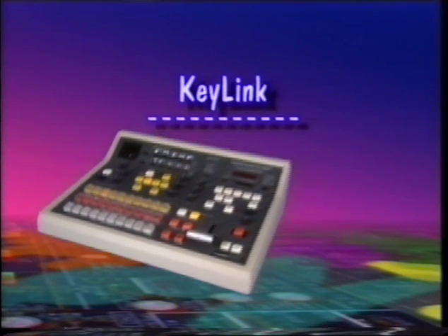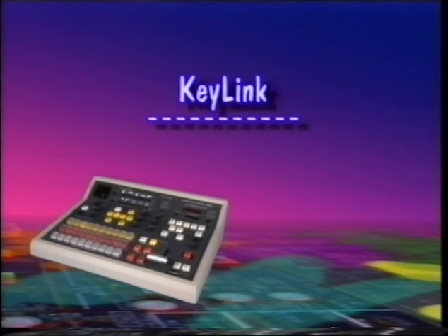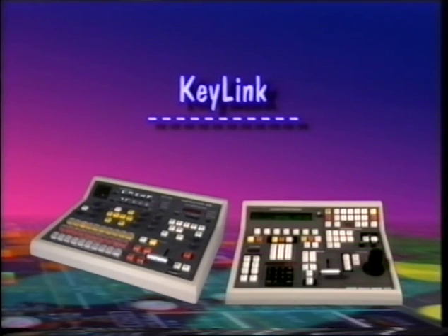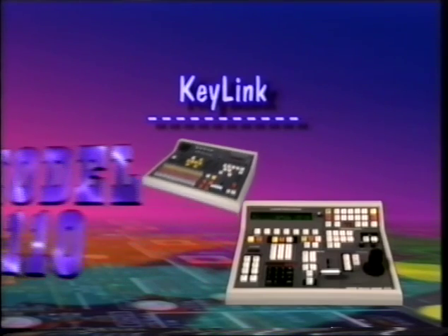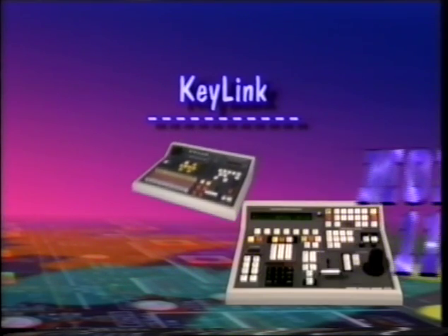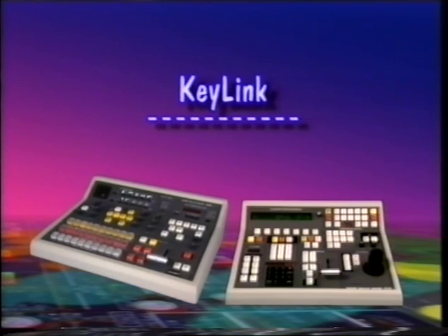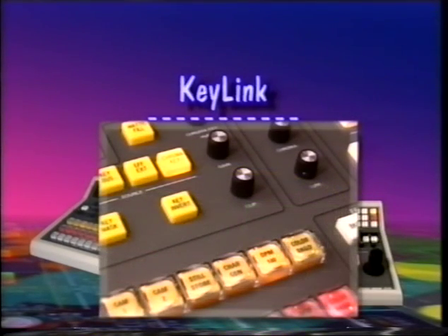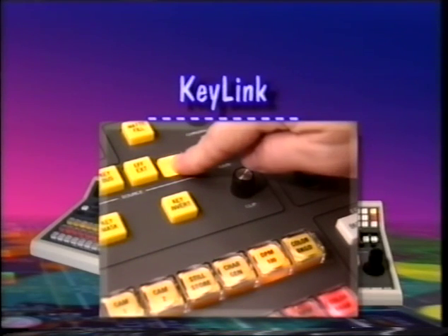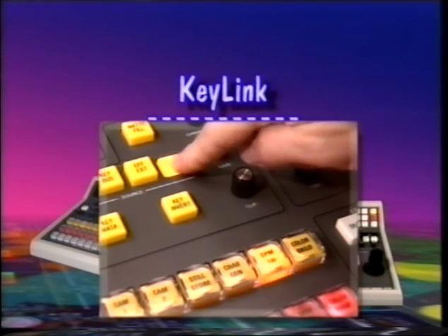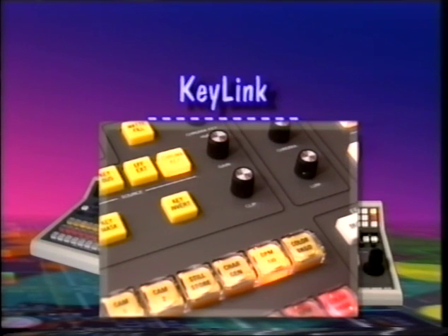Another option of interest is the Key-Link interface feature of the Model 110. If you have a Grass Valley Group digital picture manipulator, the DPM series, you can use the DPM and the Key-Link interface to fly a chroma key or an external effects key. With the DPM connected to the Model 110 through the Key-Link interface, you can activate Key-Link by holding down the chroma key or the effects external push button and simultaneously selecting the DPM input on the key bus.